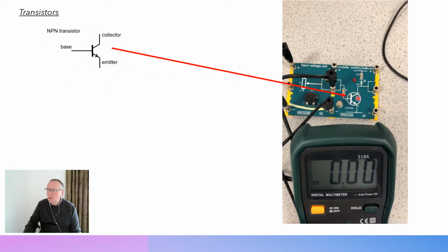And you can see on the actual Alpha board kit, it's got a circle round about it. So that might be part of the symbol, I'm not 100% sure. Probably should have checked that, never mind. So this NPN transistor forms part of this circuit. All we've got here is a variable resistor that's altering the voltage of the input to the transistor. When I click play, you'll see that I'll start increasing the voltage going to the transistor, and you want to watch this LED here.